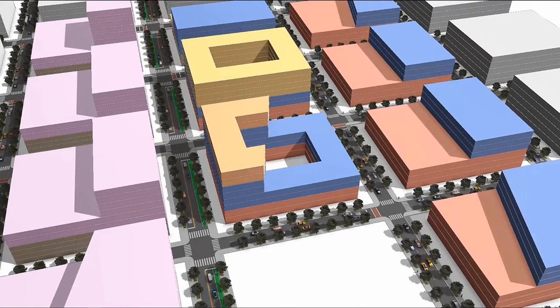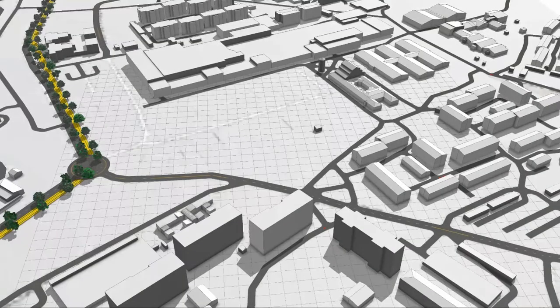And then a lot of these enhancements also work to improve the street editing in general. One of the common frustrations or requests the users had is when they were working with editing and modifying features, they select a collection of features and then they accidentally select a feature they didn't intend to select. For instance, they got a portion of a road. Now when you do undo, it actually flips between your different selection elements. So you can walk your selection back bit by bit.